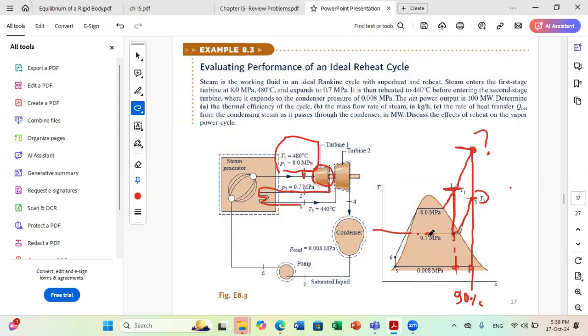So inside the dome, they give you either the pressure or the temperature with another value. They can give you, for example, the entropy or the enthalpy, etc. Sometimes you just know the entropy and the enthalpy, and you can get the conditions that you are in. So you need two properties, but inside the dome they don't give you both P and T because they are related.